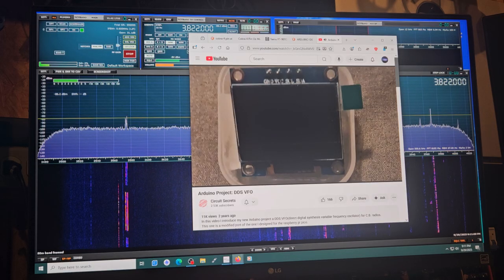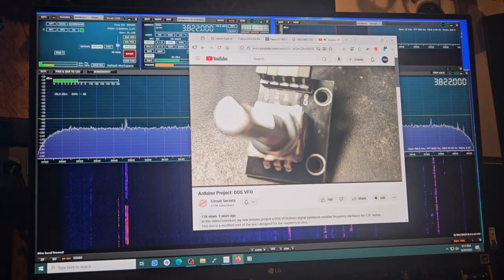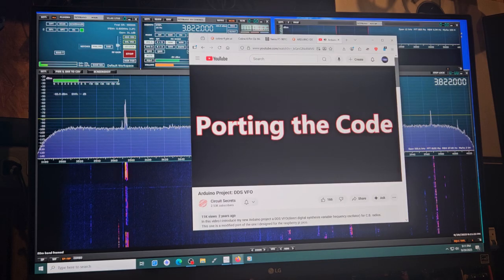Next, I tried an example sketch for the SSD1306 display, then one for the SI5351. They each worked great. Then I tossed some code together to read the encoder and output the results to the serial port. This worked as well.